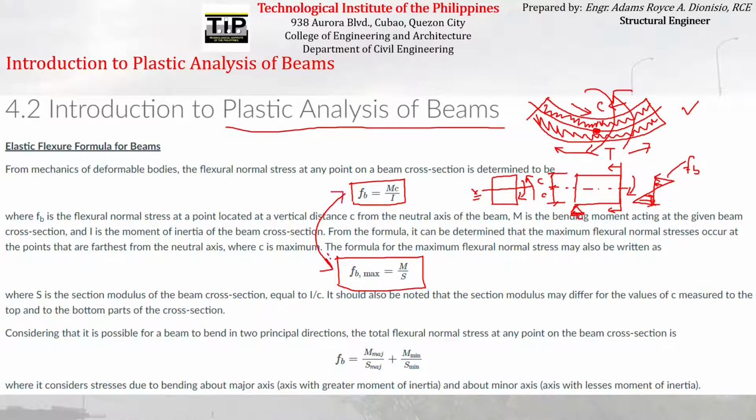From this drawing, you can already interpret that the maximum flexural stresses occur either at the top or the bottom fiber, because the distribution is triangular in shape. If I draw the figure a bit better, it looks like this. Triangular in shape, these are the compressive stresses, and at the bottom, the tensile stresses, if this is our beam.